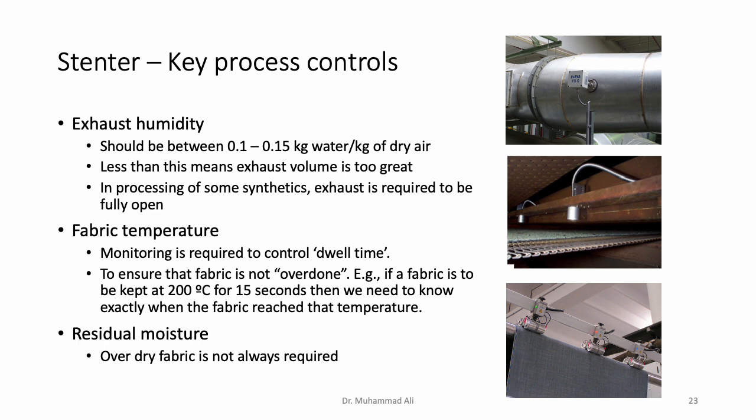Usually these are contact-based sensors, and they measure the moisture in the fabric. If the fabric is too dry, if it's over dried, then this would indicate that there is a margin for us to either increase the speed of the machine, or let's say reduce the temperature, for example.